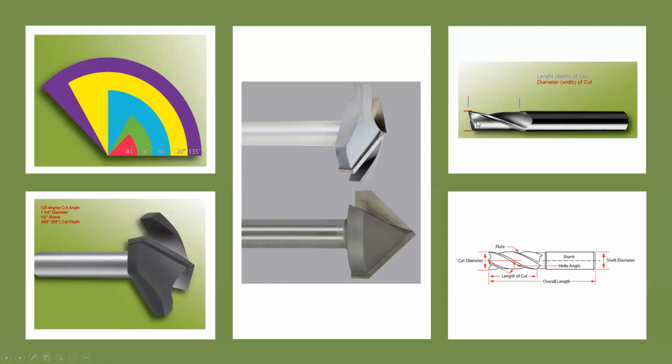I have cutting flutes that will drill into the material, but as that cutter starts to move laterally through the material, I only have cutting flutes here on the tip to remove it. So if I sunk it further in, there are no flutes up here to cut. So this is considered the shank, or would be considered as part of the overall length. So the overall length of the cutter would be from the tip of the cutter all the way back to the end of the shaft.